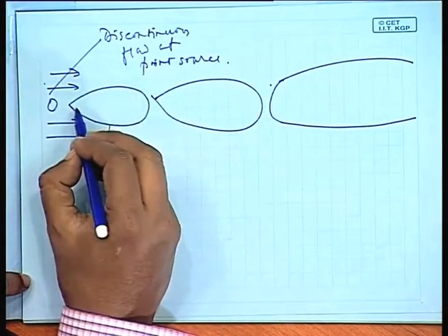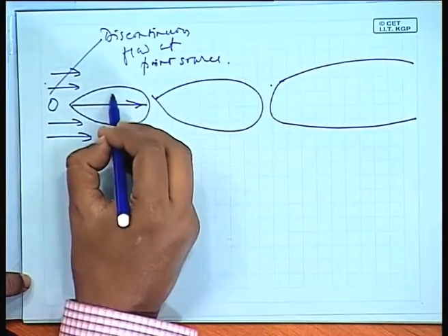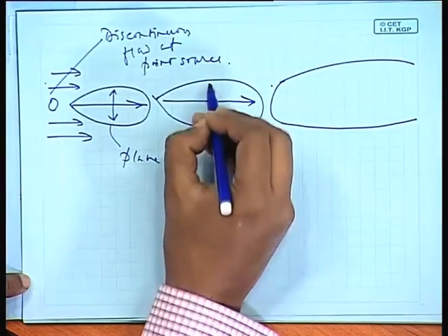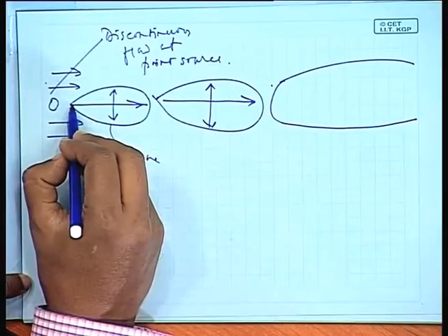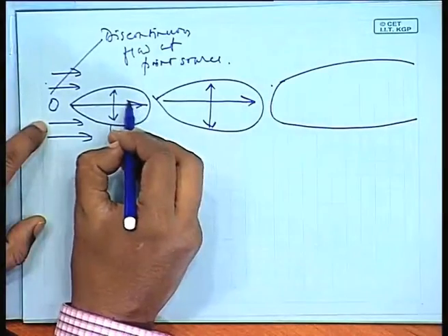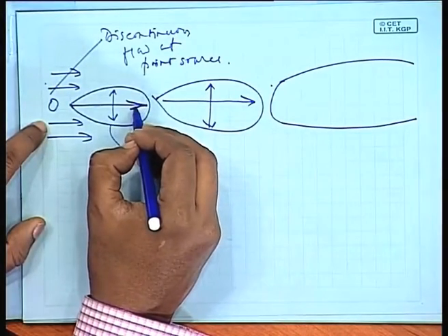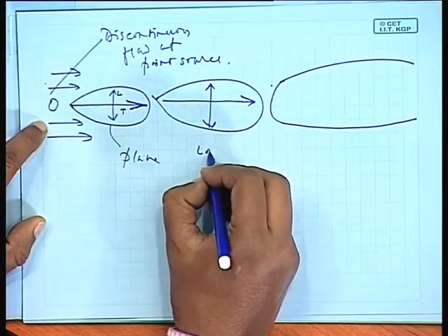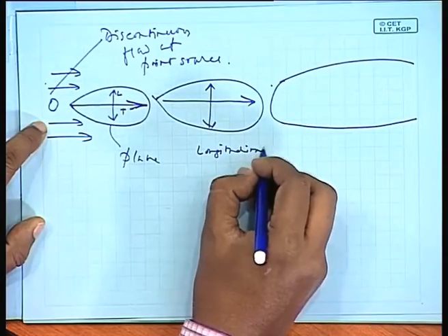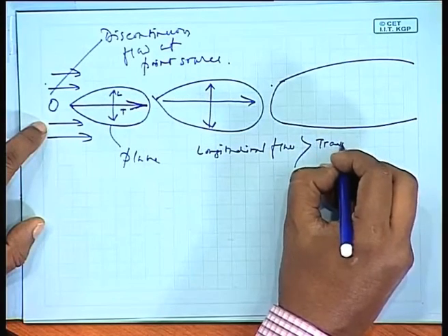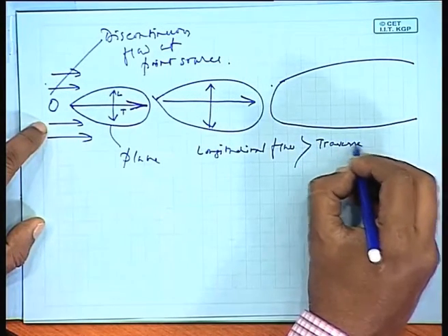This is a plume which is flowing like this. This is what is dispersion. Darcy's law only discusses the flow along the decrease in head, so it is essentially discussing mostly the transverse flow. But sometimes the longitudinal flow is more than the transverse flow.